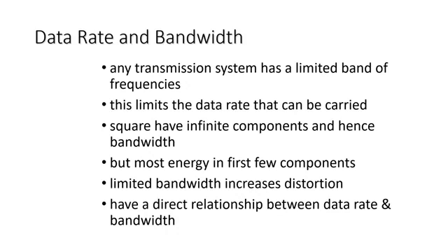In general, any digital waveform will have infinite bandwidth. If we attempt to transmit this waveform as a signal over any medium, the transmission system will limit the bandwidth that can be transmitted. For any given medium, the greater the bandwidth transmitted, the greater the cost. The more limited the bandwidth, the greater the distortion, and the greater the potential for error by the receiver. There is a direct relationship between data rate and bandwidth. The higher the data rate of a signal, the greater is its required effective bandwidth.